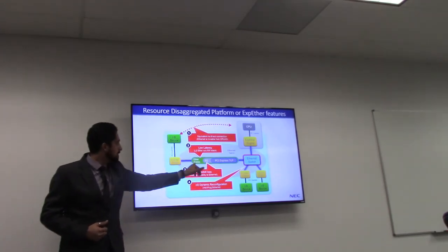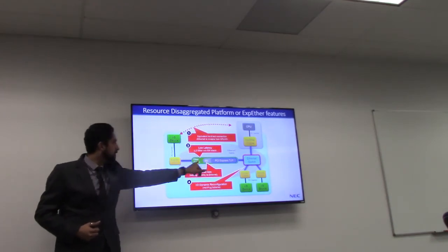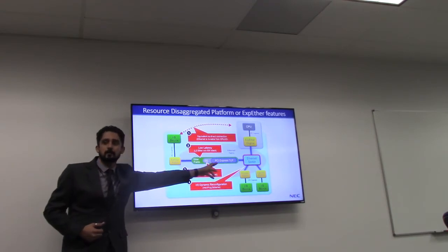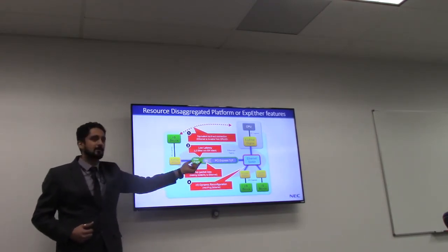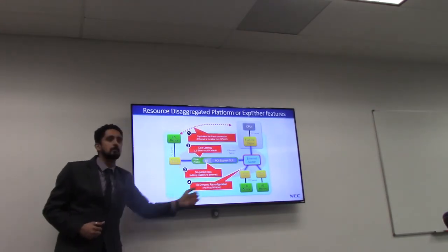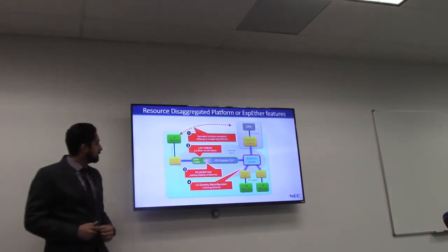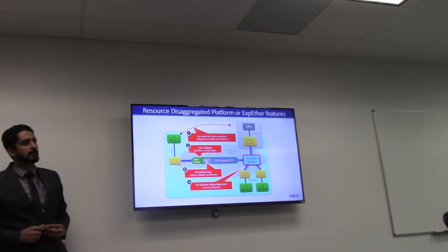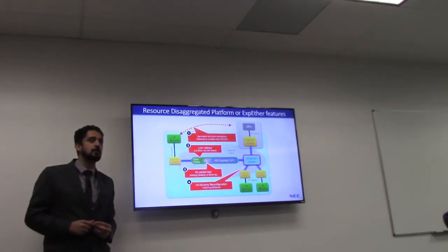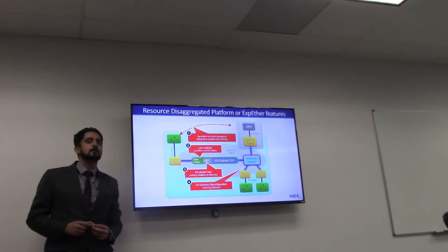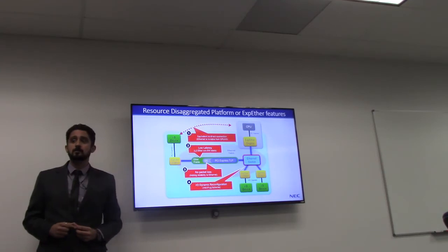So you see here is the Ethernet frame. Within the Ethernet frame, we have the Express Ether packet, which has the TLP PCIe packet. And this is all encapsulated at the hardware layer and provided to the IO device and accordingly to the CPU, and vice versa. Since PCIe is a lossless protocol and Ethernet is a lossy protocol, within the hardware we have implemented methods that allow lossless communication between the CPU and the host.